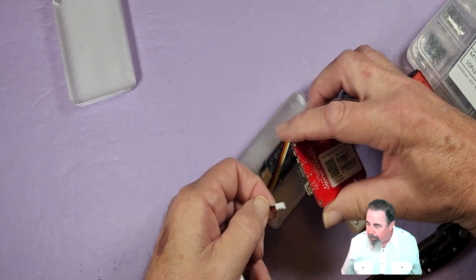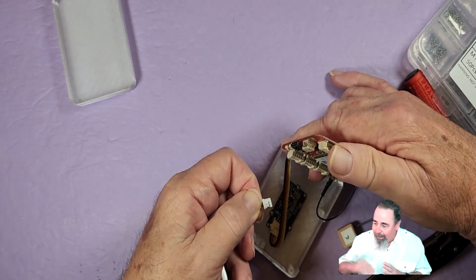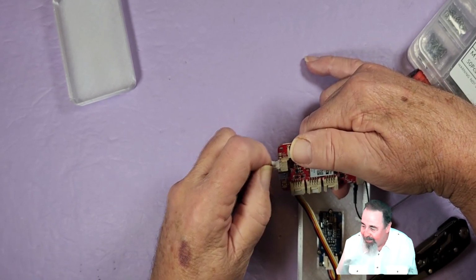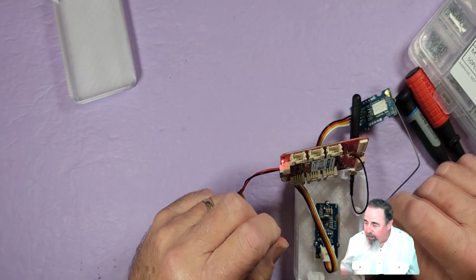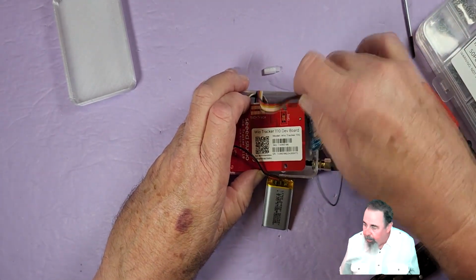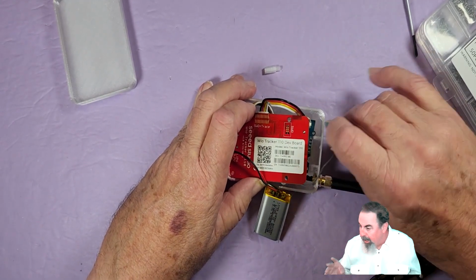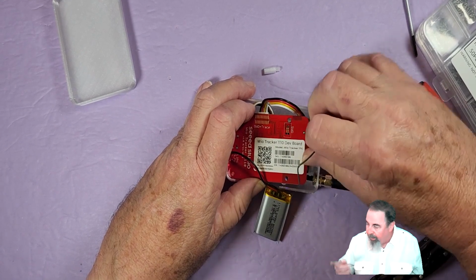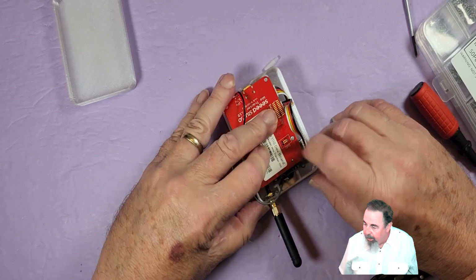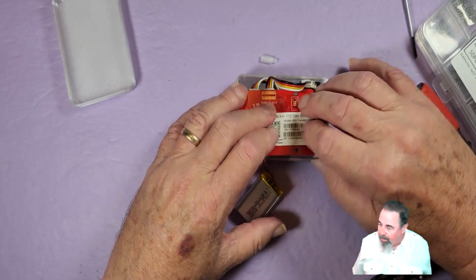I'm going to go ahead and hook up the battery, because when you put that board in the case, the battery plug is in the case. I wish that weren't the case. I wish you could unplug the battery just by taking the back off, but you got to be careful putting this GPS board in here. Make sure not to short it against the other display board or the WIO 1110 board. And then there's a little pocket there to drop the GPS antenna right next to the LoRa antenna there.